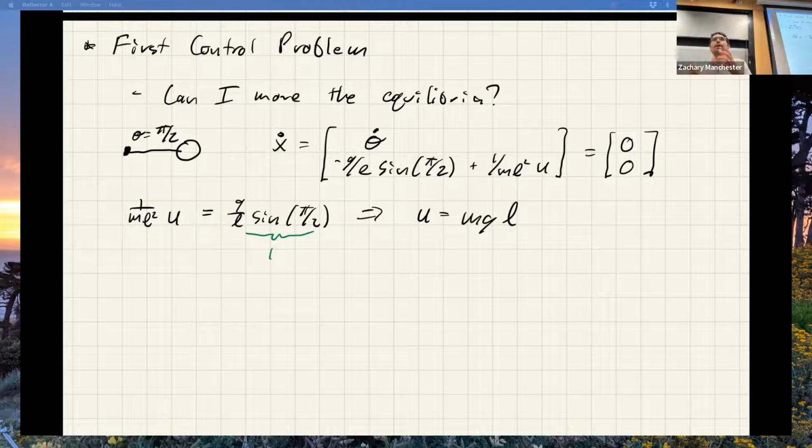But you could imagine, if I have no control input, there are these two equilibrium points. As I start cranking on u, if I fix it as a parameter in the dynamics model, I can remove, create, destroy equilibria. You can imagine if I crank it up really high, so I have a super big torque that's bigger than mgl, now it's just going to spin around forever, and I've gotten rid of the equilibria entirely. So there's all kinds of weird stuff you can do here.